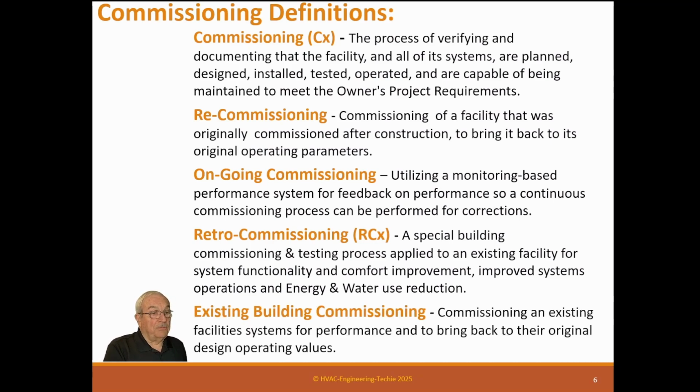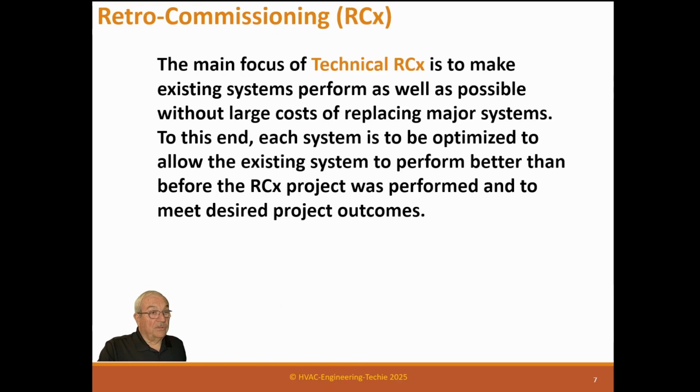And existing building commissioning, which ASHRAE has a standard for, is commissioning an existing facility's systems for performance and to bring them back to the original design operating values. Again, they're trying to use new building commissioning processes on an existing building. If you're just trying to bring it back to its original design values, this will actually work. But that's not what we're doing in retrocommissioning. If you do that, you will not fix the building.